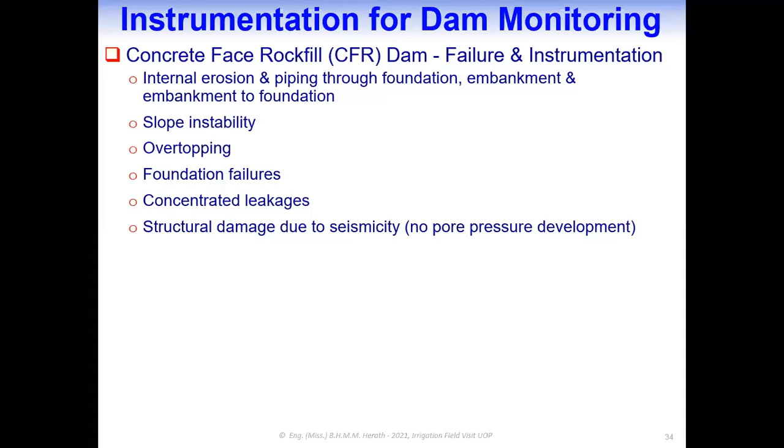Overtopping can wash off the downstream materials and cause the face slab to be in an unstable condition without providing necessary support for it. And then foundation failures and concentrated leakages and any other additional damages due to seismic activities. However, the main thing you should note here is that for concrete face rockfill dams, the face slab is acting as the impermeable membrane that holds the waters